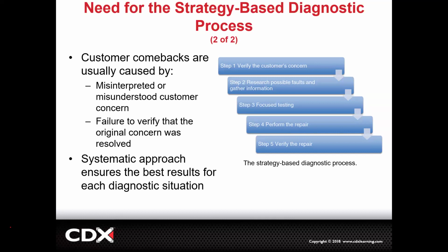So give it a good overview, right? Don't jump in there like rookie techs. A lot of times what they'll do, they'll be like, oh, the AC doesn't work, hook the machine up, hit recover. And you're going to pull the 2 pounds out of the system and be like, oh, well, it had refrigerant in it. All right, cool. But you wasted all that time to verify that there was refrigerant in it. That is not how a more well-seasoned technician would start. Even though I'll confess, 8 out of 10 cars that have warm air concerns probably have a leak and they're probably low on refrigerant. I still wouldn't waste all that time doing that process.